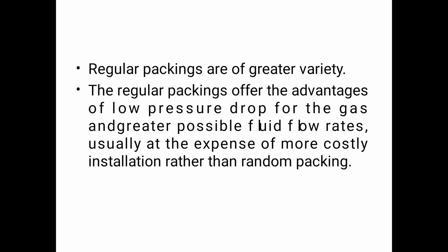Regular packing offers greater variety. The regular packing offers the advantages of low pressure drop for the gas and greater possible fluid flow rates, usually at the expense of more costly installation than random packing. The packings are arranged properly.